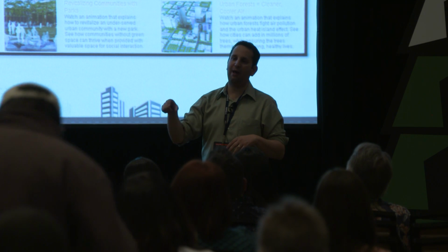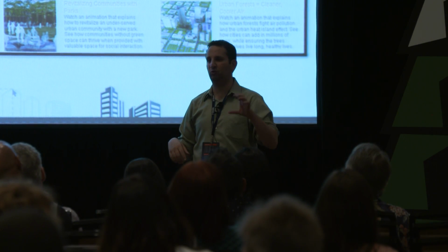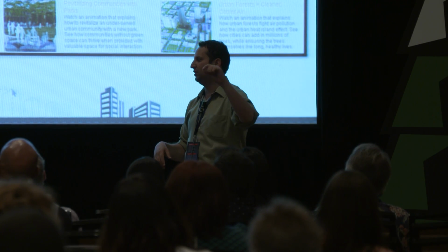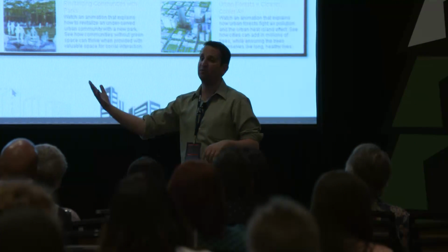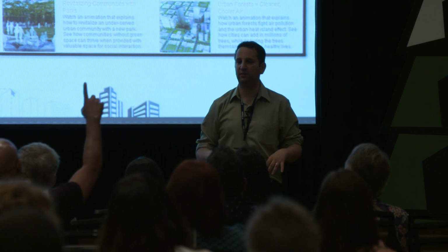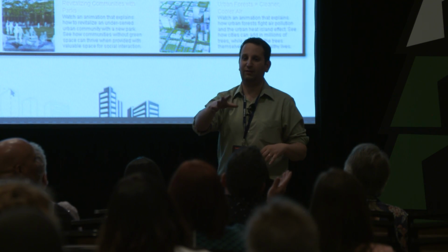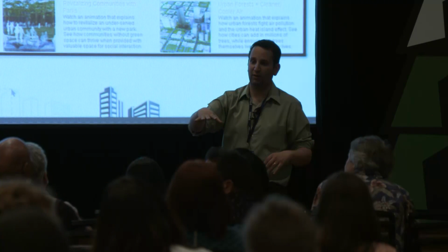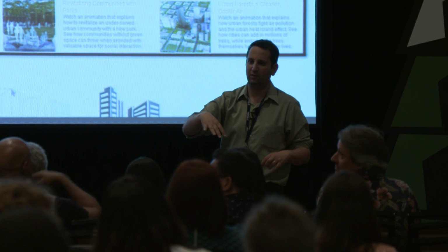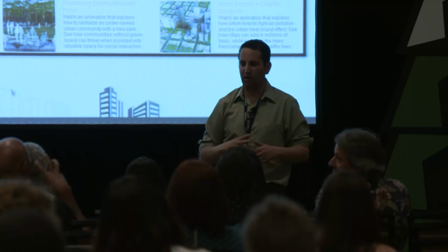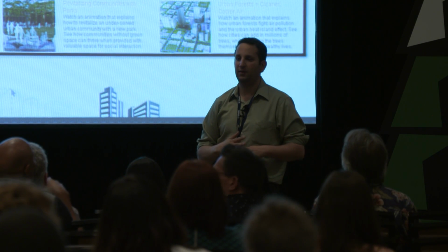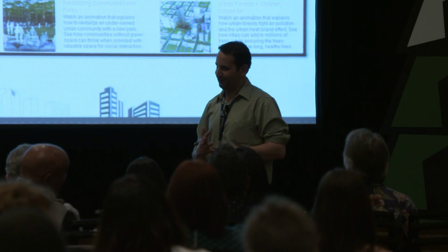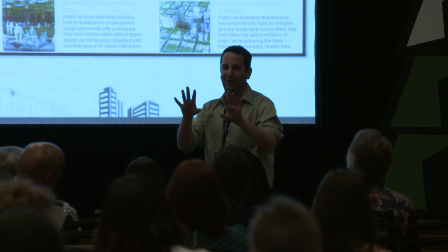Grab the line work, hit the move tool, and you can move something automatically to the 0 axis. You lose the georeference, though.